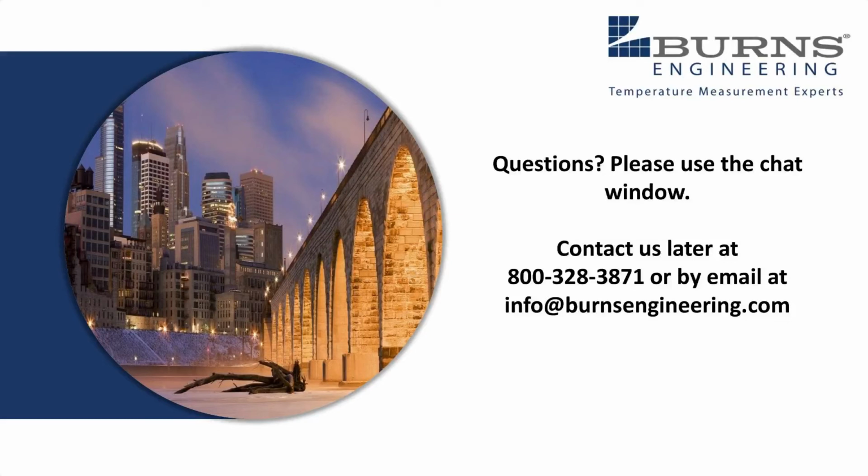So the way we do that test and the way the standards define it is we typically take the probe, stick it in an ice bath and cool it down to 0 degrees C. And then we put it in water moving at 3 feet per second, at room temperature. The time it takes for that probe to respond to 63.2% of that step change in temperature is the time constant. So it'll take that wire wound sensor 4 seconds to get from ice to 63.2% of that temperature change.